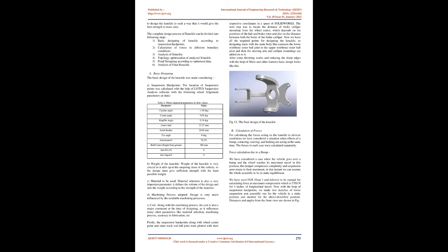Rear and side impact. For rear and side impact analysis, it was assumed that some other vehicle comes and strikes our vehicle. In this case, the impact will be of the second type, that is the impact of the roll cage with a deformable body, so the impact time will be 0.30 seconds. Then the impact force F will be as follows.